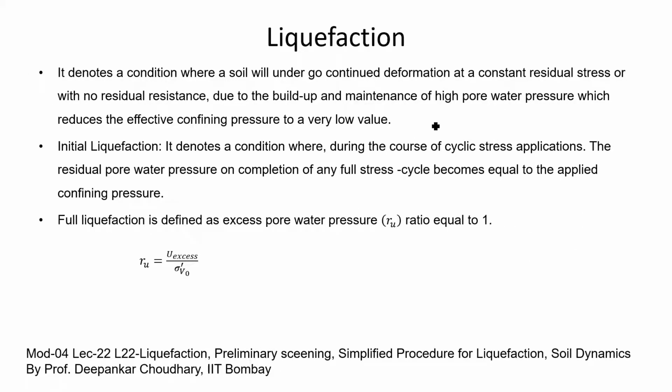Now the next term is liquefaction. Liquefaction denotes a condition where a soil will undergo continued deformation at a constant residual stress, or with no residual resistance, due to the build-up and maintenance of high pore water pressure, which reduces the effective confining pressure to a very low value. So liquefaction is initiated during the course of cyclic stress application.